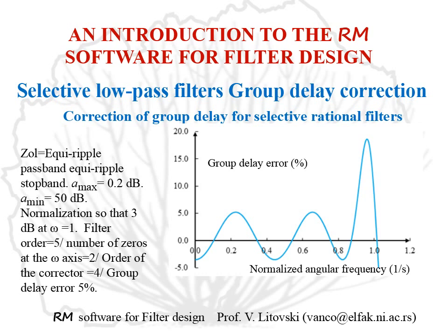Here is the group delay error exposed in order to see that due to the nature of the group delay characteristic of the original filter, non-corrected, it's difficult to get symmetrical 5% of both sides during the iteration process.